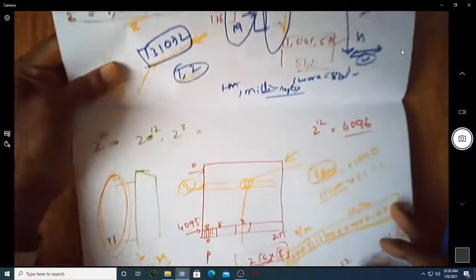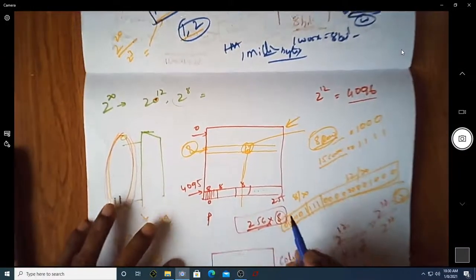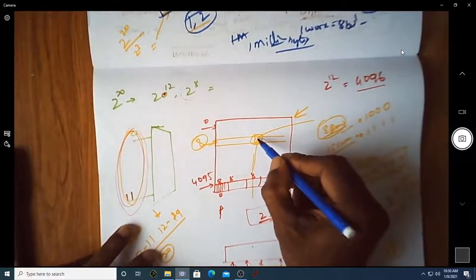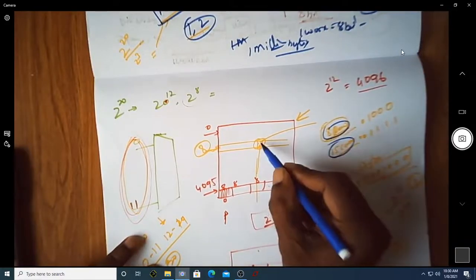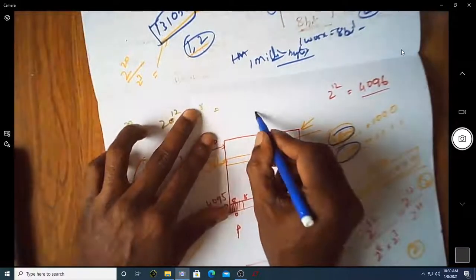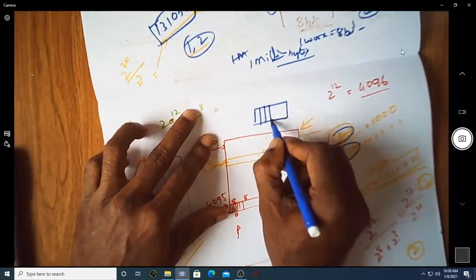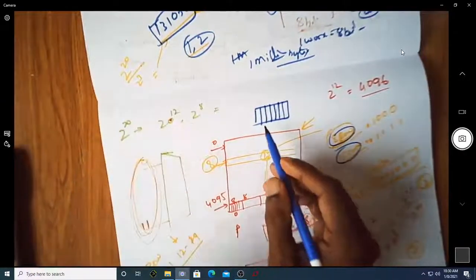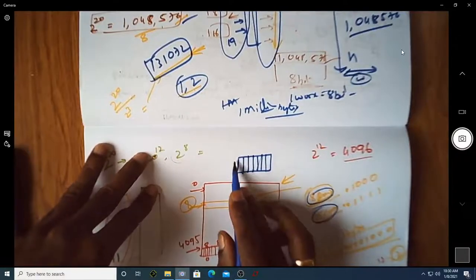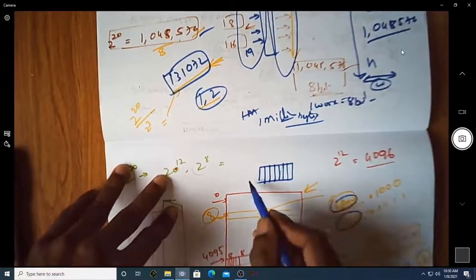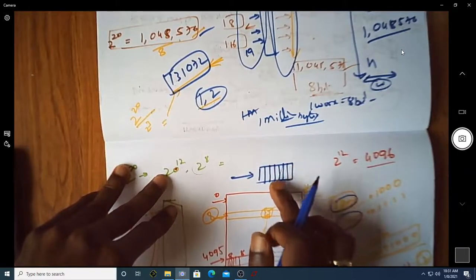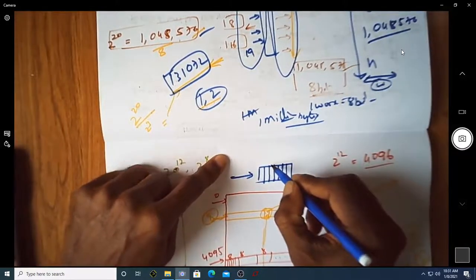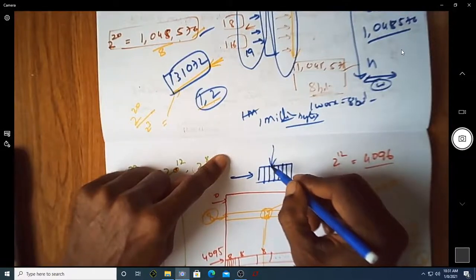Assume that this is the 8th row and 15th column location, which is a word corresponding to 8 bits of data. If you want to identify this particular word, there should be a word line which will identify this is the word you are accessing, and you are supposed to have a bit line to access that particular bit.